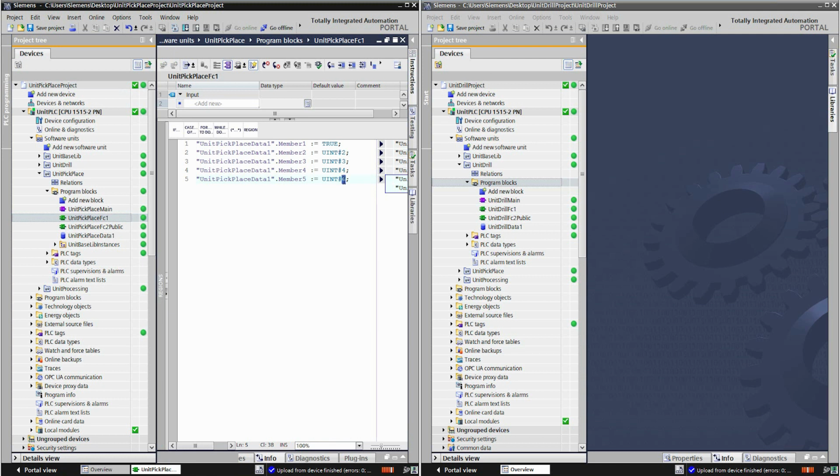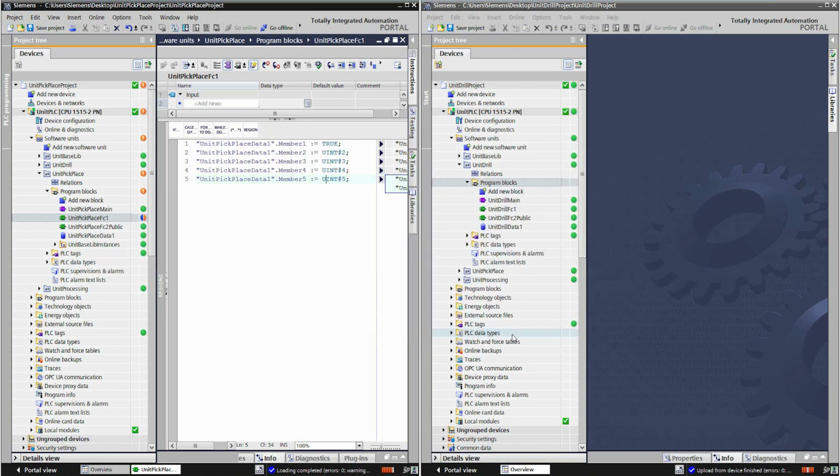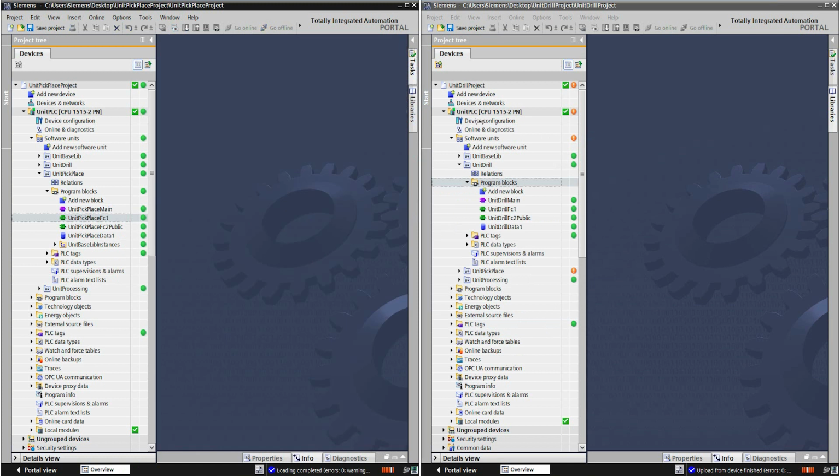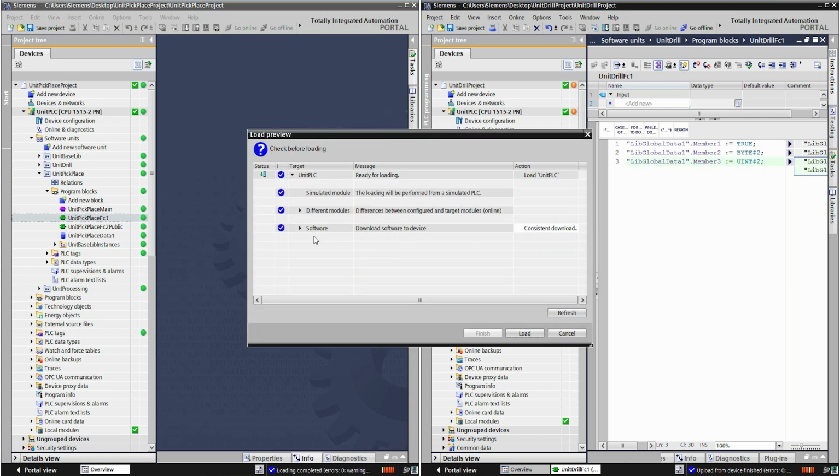Due to the modular project structure and logical units, the TIA Portal compiler only needs to care about the correctness of the elements used in the unit to ensure the consistency. That means a unit download will proactively exclude elements or blocks which are not relevant for the unit execution. A synchronization of possible changes from the other colleagues is not necessary anymore. The software elements of the other independent units will be kept inconsistent regarding the online PLC project. This behavior essentially improves the performance while commissioning thanks to the partly consistent download of the software changes.